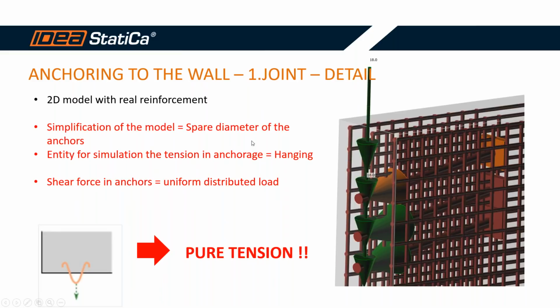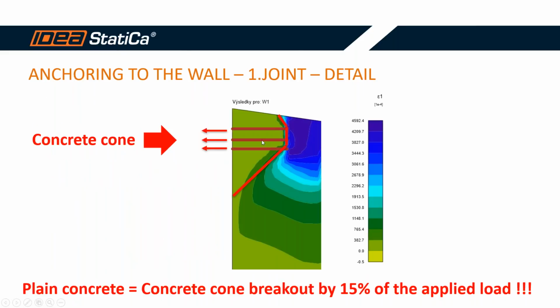So I will come back to the IDEA StatiCa Detail application, but at first I would like to show you that we did some analysis for a plain concrete in our application Detail, and you can see that the concrete cone appeared here at 15% of the applied loads, right? So without reinforcement, the concrete cone breakout will appear. So it confirmed the claim in the application Connection.